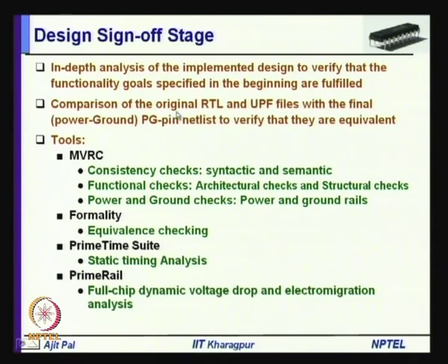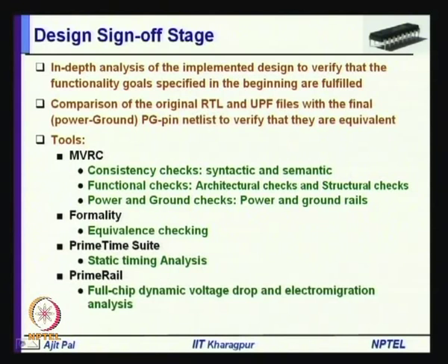Then you have to compare the original RTL and UPF files with the final PG pin, or power ground net PG pin netlist, to verify that they are equivalent. That means you have to perform verification of the intent with the actual implementation. That verification can be done with the help of several tools, such as Formality.